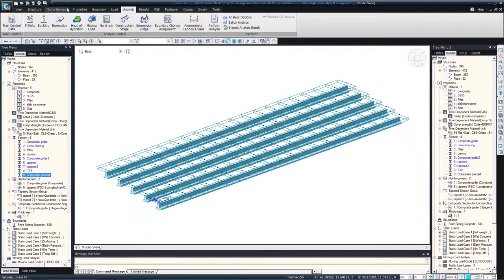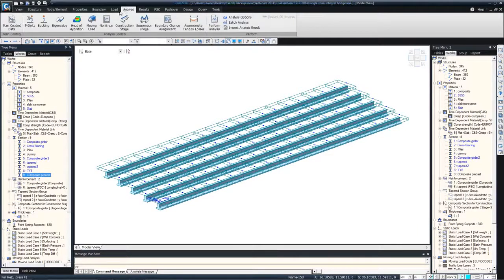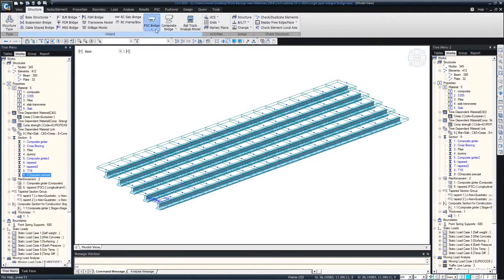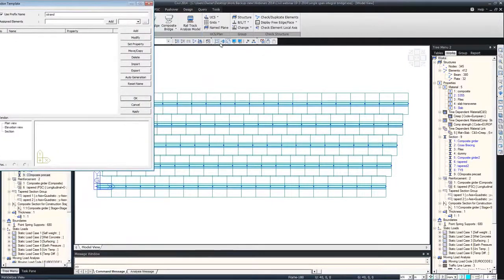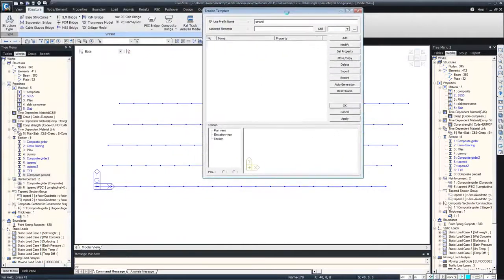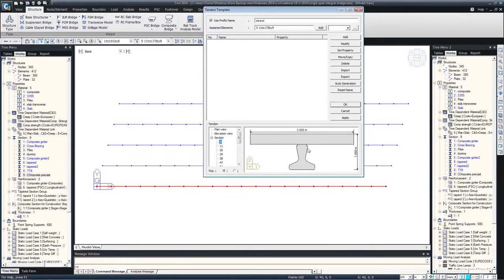Okay, so those who have been using the 2013 version of the software, there is a new development in the 2014 version, which is the predefined tendon templates. So for any given precast section, we can just simply select the tendon template here. So I've selected this option and select the members that we want to assign the pre-stress with. So maybe turn on the line view, and it's good to create groups for each girder. So that's the girder selected. You can see the section view.